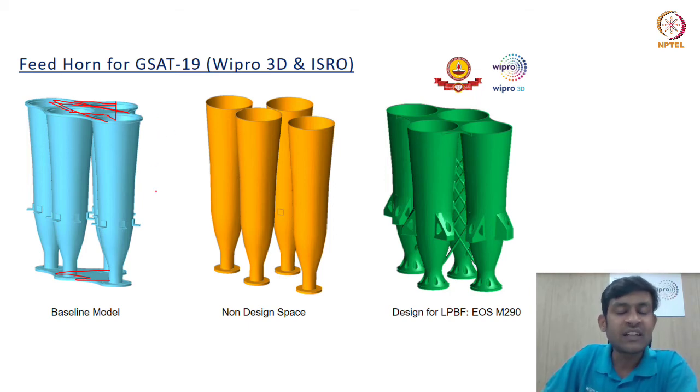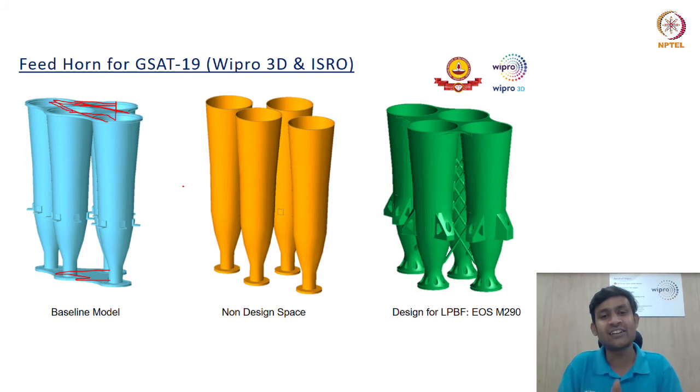Now, in order to maintain this, we need to weld it using very high precision fixtures. So making fixtures is mandatory in this case for my component. Making fixtures is adding time and adding cost to the manufacturing process. So now, by clearly understanding the application, I know what the design space is.